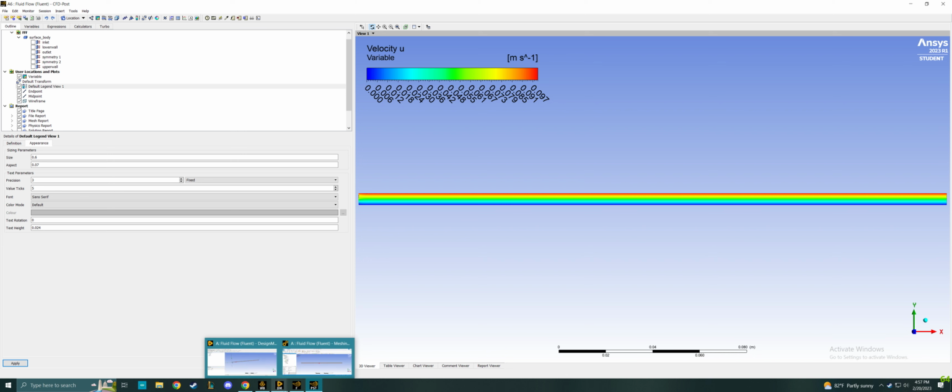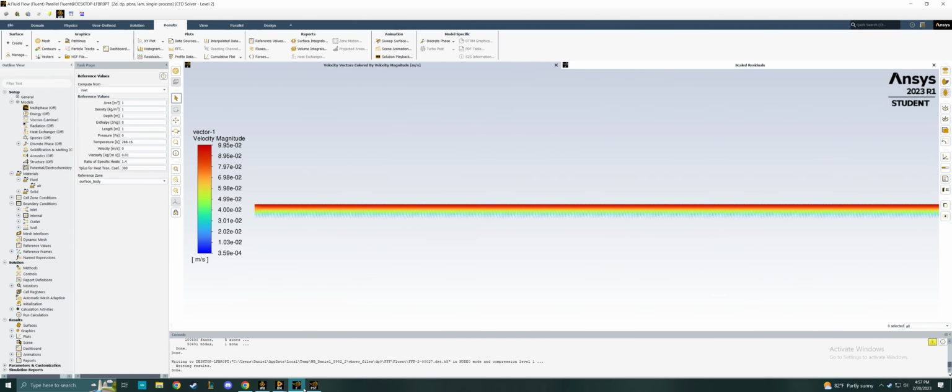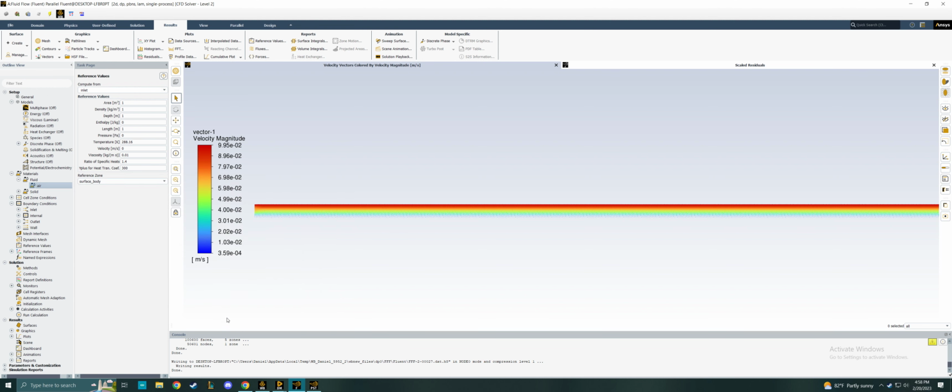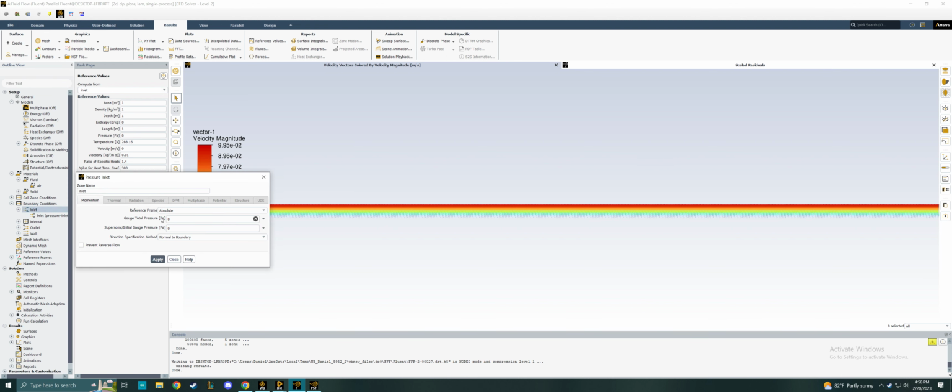Now, if we want to do a combination of both of these flows, which is the final part of this project, we're going to go back here into this app and then change the material right here, fluid air edits. We're going to set this viscosity to 1e to the -5, which was what it was originally before we changed it. We want to go to boundary conditions, and on inlets, we're gonna edit this. Oh, my bad. Right here, inlets. We're gonna set the type.